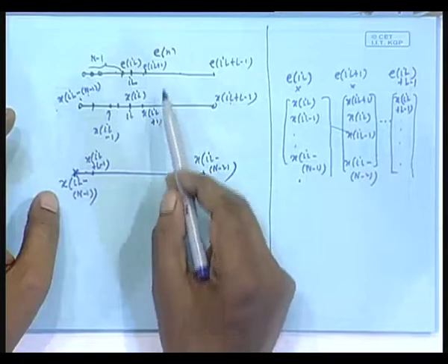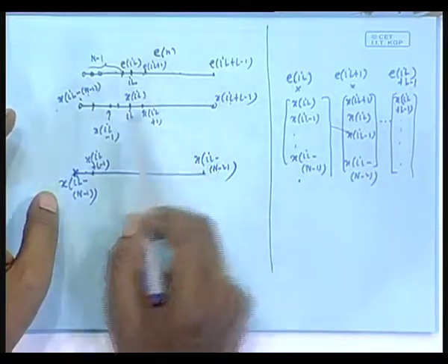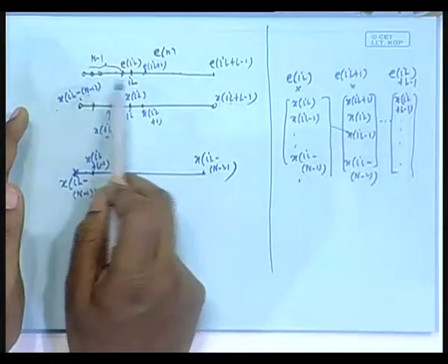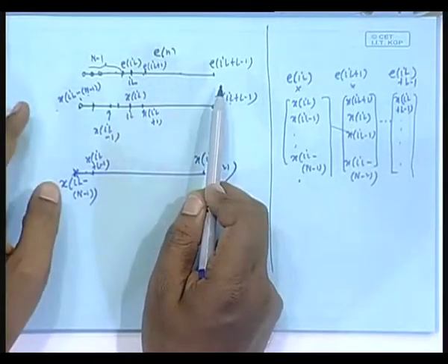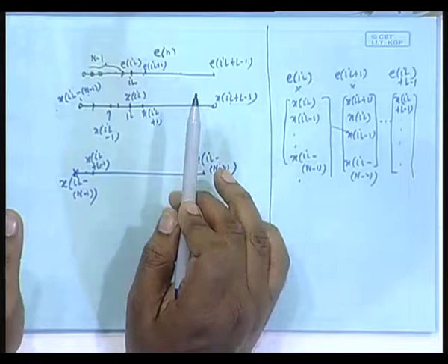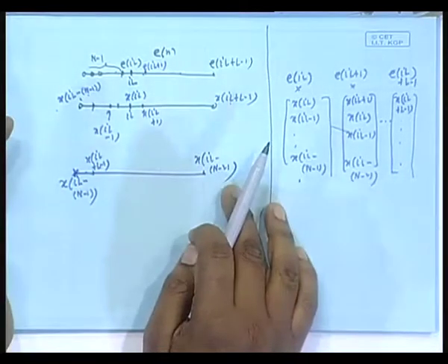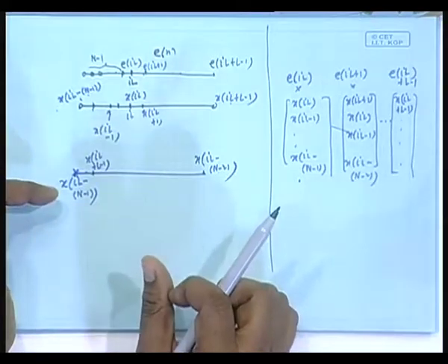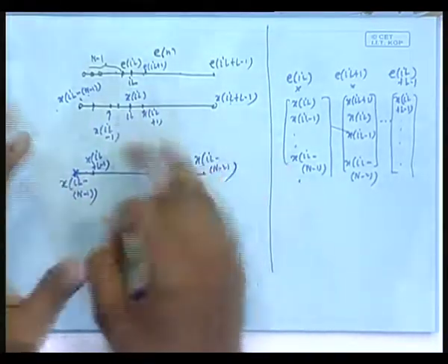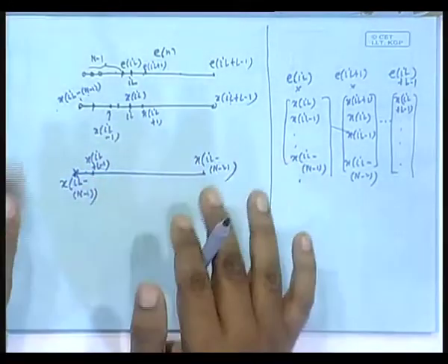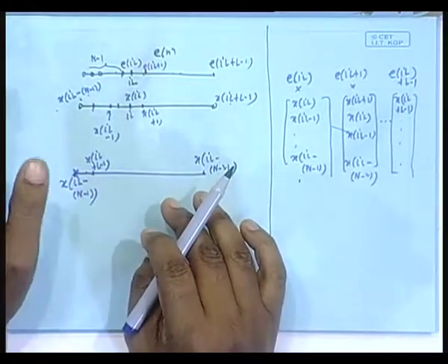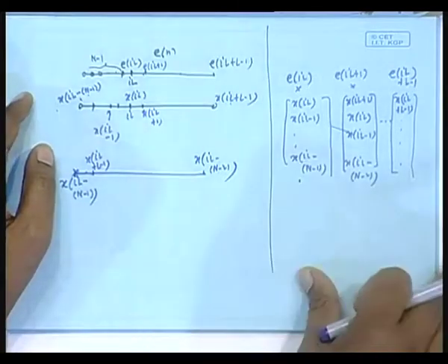So, that means I have to do a circular convolution between the two. What is the DFT of this? I can take the DFT. You give me the E sequence, the error sequence, I add some extra 0s, make it a bigger vector of length capital M. I can take an M point DFT of that. But how about this guy? It has got some extra data. Earlier I was living happily with an L point data vector. Now, some extra garbage has come and they have got flipped and the order has been changed, isn't it? So, what do we do to that? That is the question. Now, I show you some beautiful property of DFT.